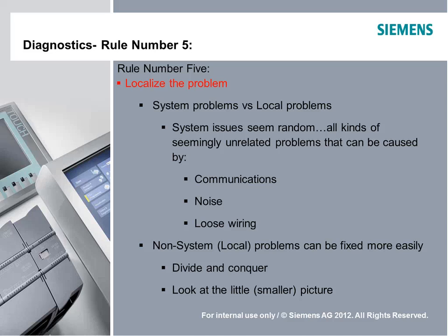So we're seeing values coming in from a thermocouple, for example, that couldn't possibly be real. When the machine's control system sees a temperature jump up 100 degrees, maybe it shuts down. Those could be caused by noise, and it could be a wiring issue, a wiring routing issue, or loose wiring. Loose wiring gets us into the possibility of an intermittent fault, and we're going to talk about that in a minute.